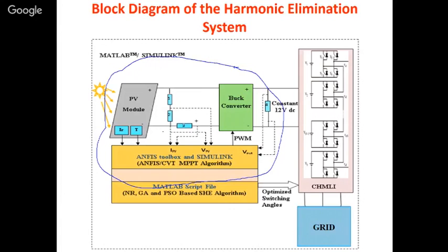Now our main aim is when these are connected, in our laboratory we made the output voltage constant at the output end. Without a battery we tried to make it constant, but it cannot be made perfectly constant. We were trying to take around 12 volts as output, so we had a constant voltage tracker. At the output end we had a sensor, and that value we took inside and compared with a reference. If the value was above that reference, that is above 12 volts, we decreased the duty cycle and tried to track it to 12 volts.